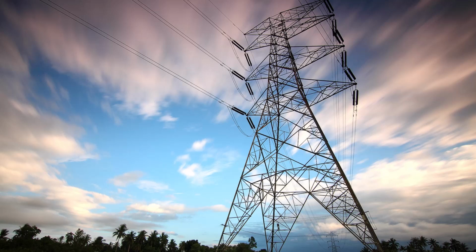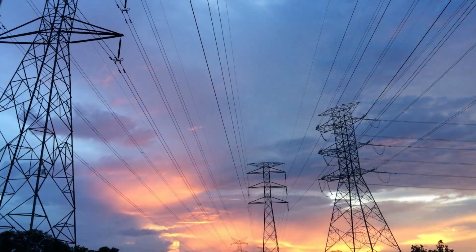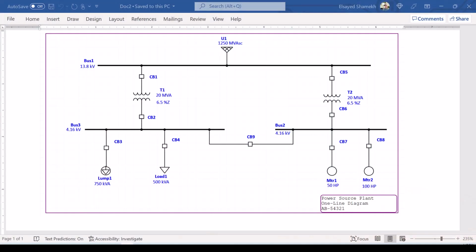Also, for the purpose of network modeling, constructing the one-line diagram is the first step needed to start performing any analysis. So imagine yourself as the engineer working on a project to examine the robustness of the power system or to examine the possibilities for future expansion or modification. Then one of the first tasks you may perform is to obtain a copy of the facility's one-line diagram and start transferring the data from the one-line diagram into your ETAP model.